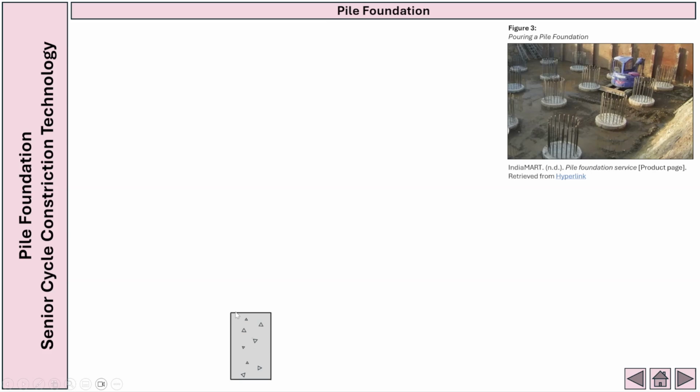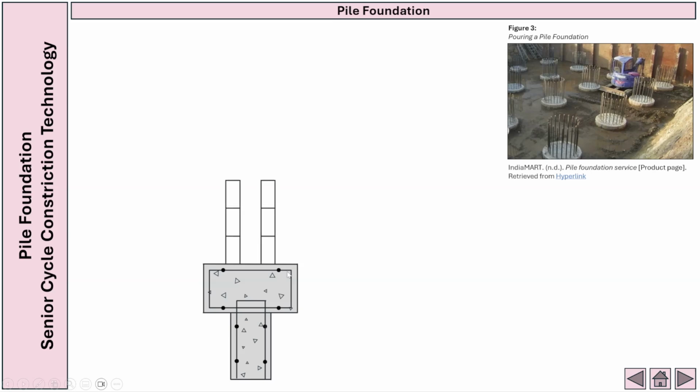On top of this pile, we're going to have our 600 by 350 reinforced ring beam, and we can tell that it's reinforced using our steel here and our circles. On top of this, we are going to start our 350 cavity construction. So in the center of our pile foundation, we have got our 3 blocks, our infill, and then our 3 blocks then as well, and these blocks are going up 200 millimeters each.